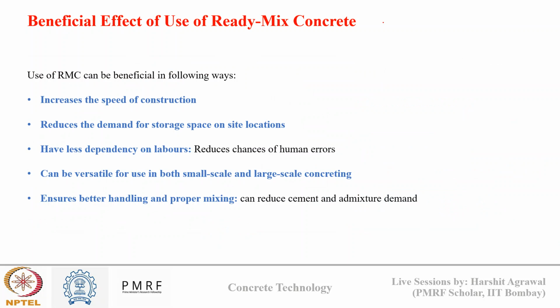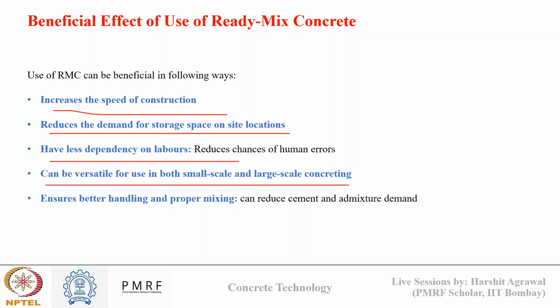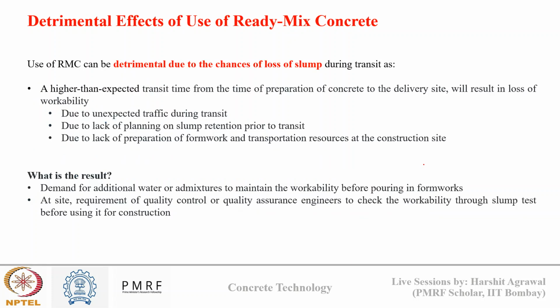Now, what are the benefits of using RMC? It increases the speed of construction, since two things are working together. It reduces the demand for storage space on site, since we don't need to store anything on site. We are directly using ready mix concrete, so it won't require any site storage space. It has less dependency on labor, which reduces the chances of human errors. It is versatile for both small scale and large scale concreting, as we saw earlier based on the mixing truck, and ensures better handling and proper mixing, which can reduce my cement and admixture demand also.